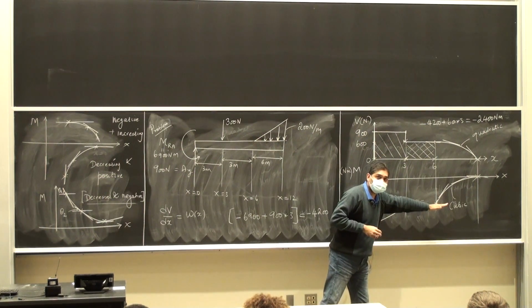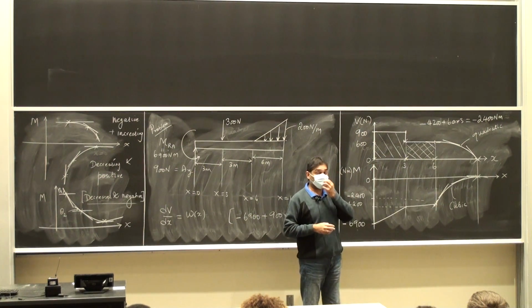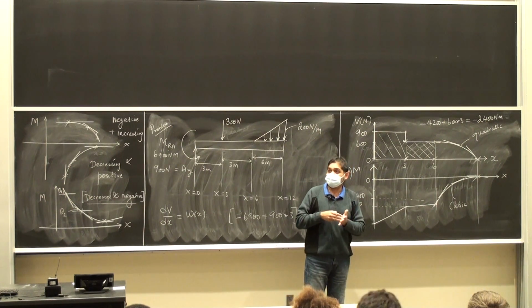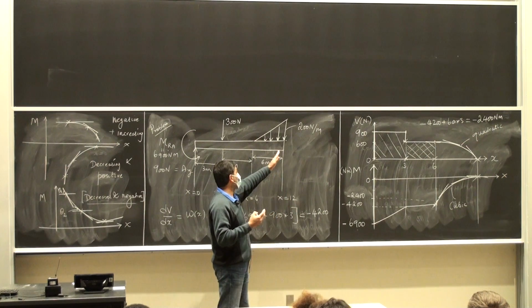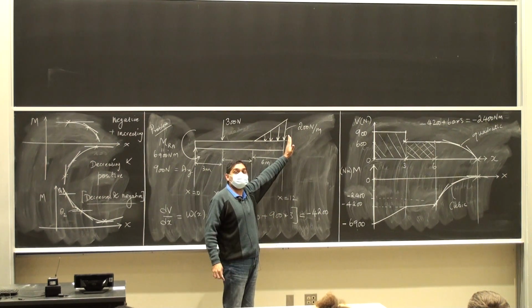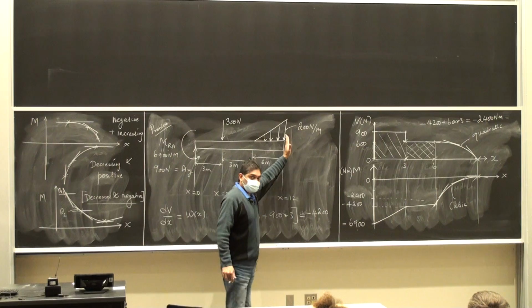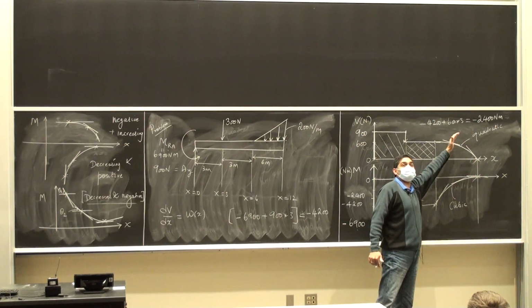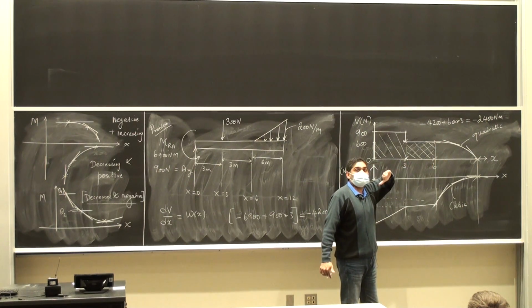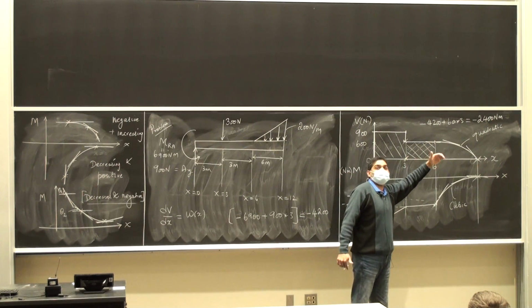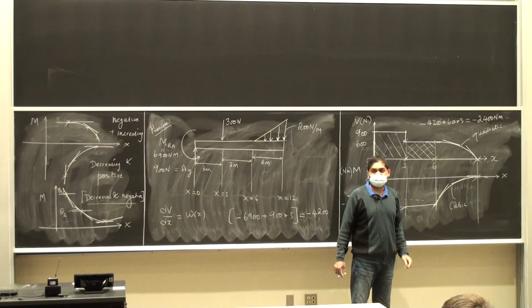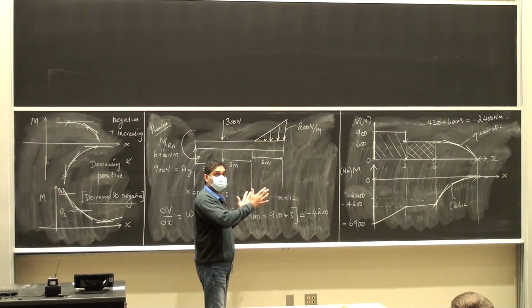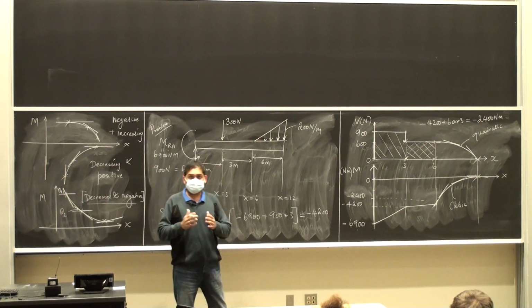Straight line. Lastly, I know that my answers are correct because my shear force diagram closed. So I know that I have to go back to 0. Why am I going to 0? Because there is nothing else here at the end of the beam. There are no couple moments here. So I go in the manner of a cubic. Because the shear force is a quadratic, the slope of my cubic is decreasing because the shear force value is decreasing. Not many calculations involved, just inspection and looking at the equations of shear forces and bending.